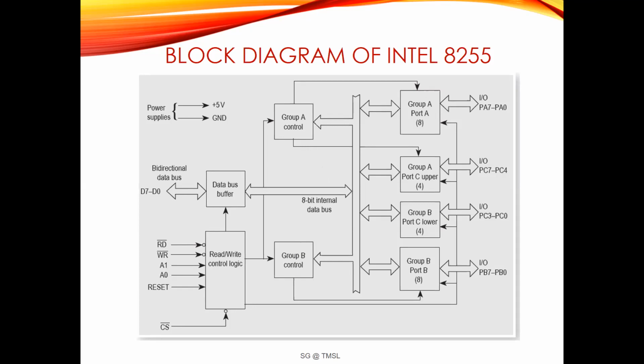There is another register called control register, and the contents written into this control register decide the operating modes of the three parallel ports.